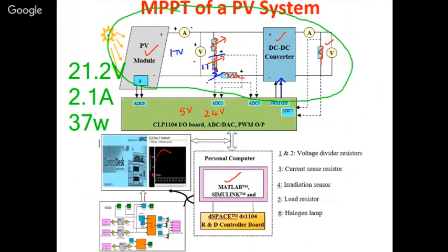You put a pot there and you simply turn the pot and see, put a multimeter also, and just measure what is the current flowing, accordingly what is the voltage drop, and accordingly you will be giving it inside the controller. Okay, is it clear?